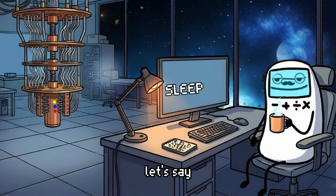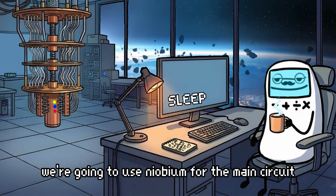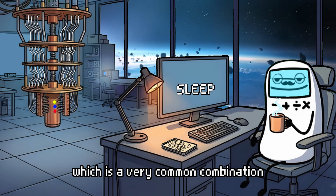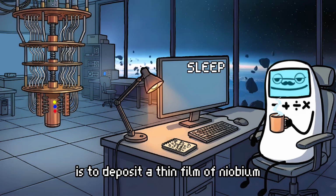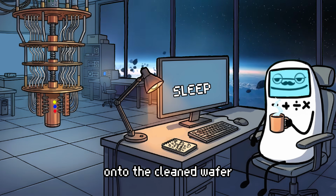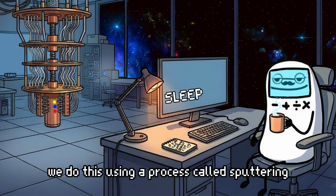So let's say we're going to use niobium for the main circuit and aluminum for the Josephson junctions, which is a very common combination. The first step in making the circuit is to deposit a thin film of niobium onto the cleaned wafer. We do this using a process called sputtering.